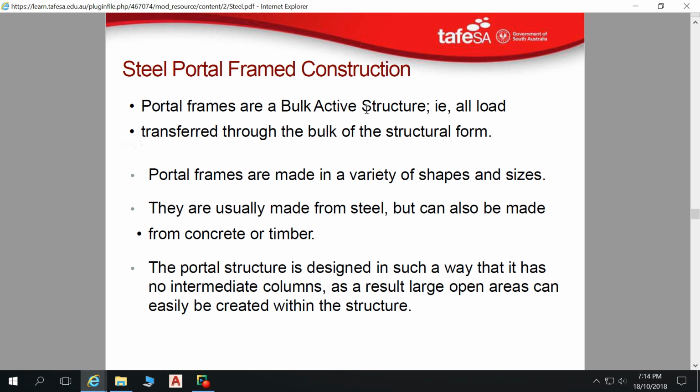Sometimes we'll have a timber framed building, but then we want really big windows in that timber building. One way to achieve that is with introducing a steel portal frame within that timber building, and you see that a lot now within residential construction. You see a predominantly timber frame, but then these heavy red steel sections within the house frame there.